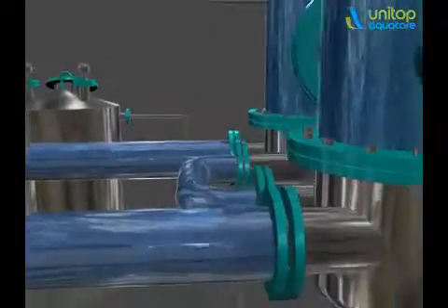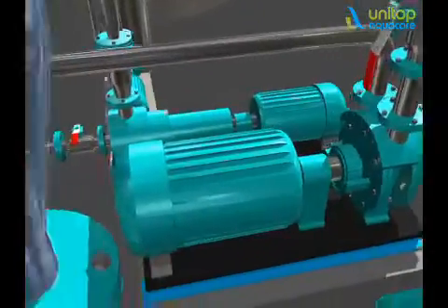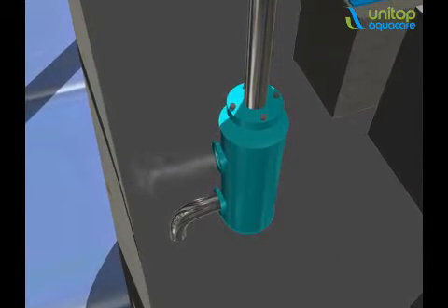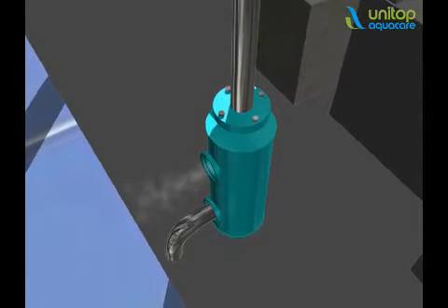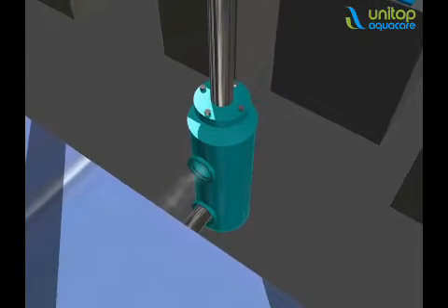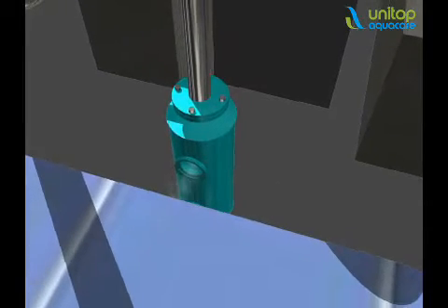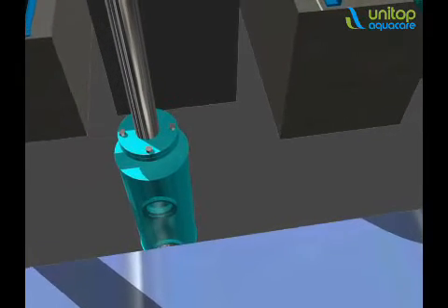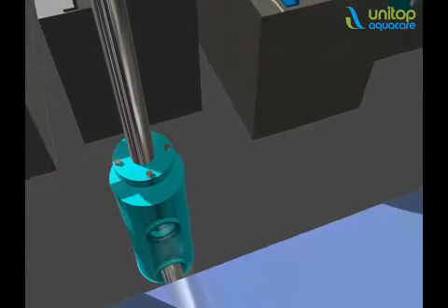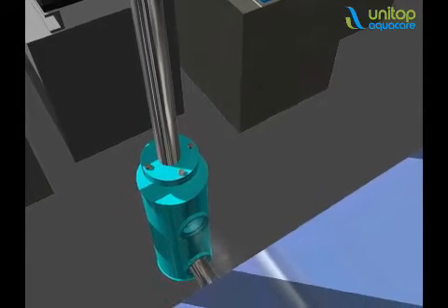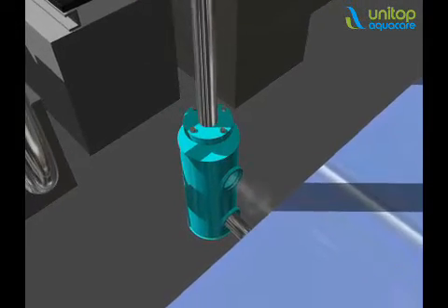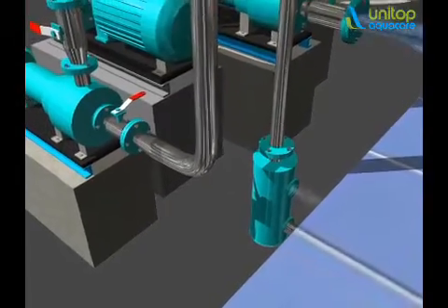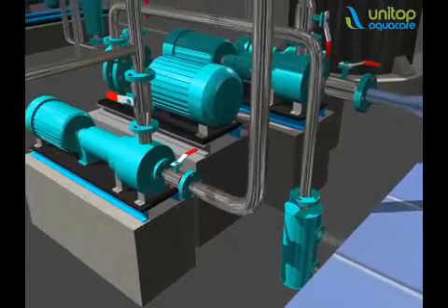Importance of applying the vacuum in the system. The air removal from the system is decisive for efficient working of the evaporator. The air has a low heat transfer coefficient and can drastically affect the evaporation rate. Also, leakage of air in the system results in lower vacuum, which in turn results in a lower temperature difference between each effect, resulting in a drop in capacity. This vacuum is produced by a water ring vacuum pump connected to the condensers.